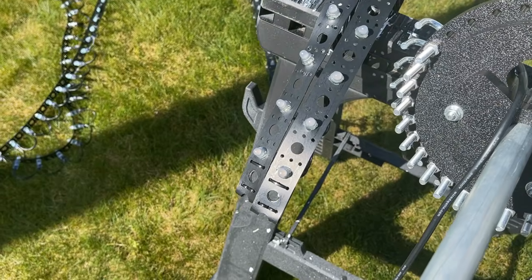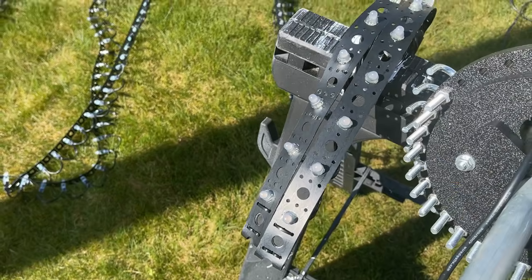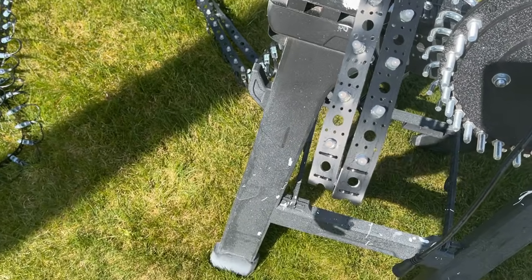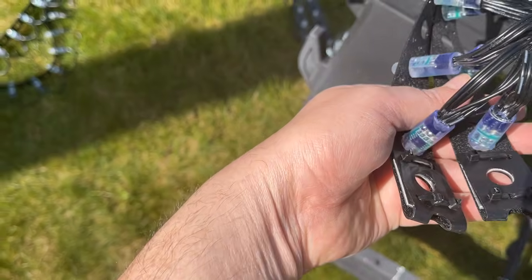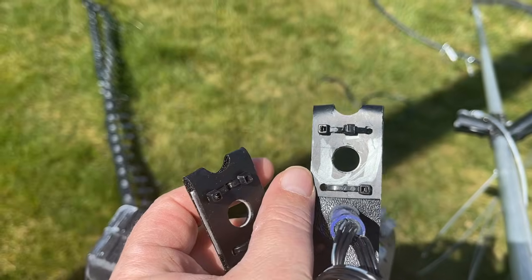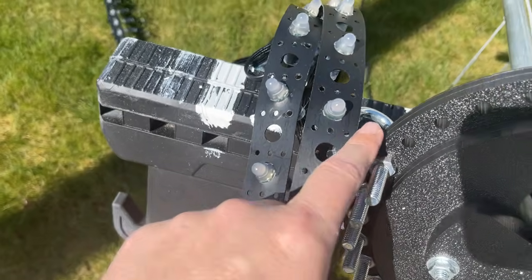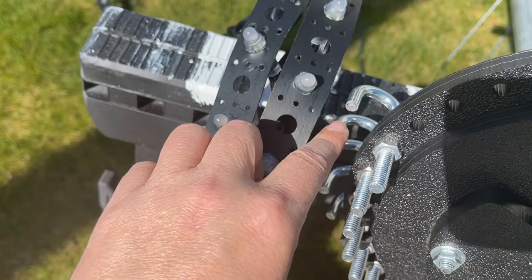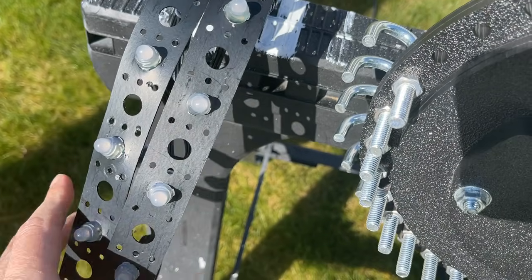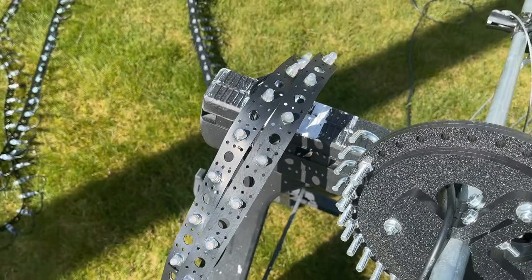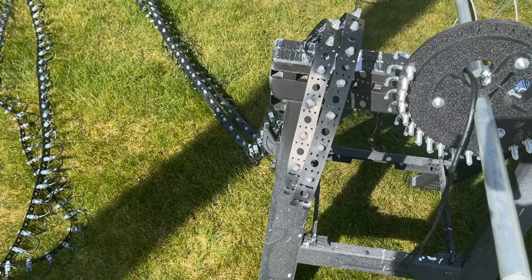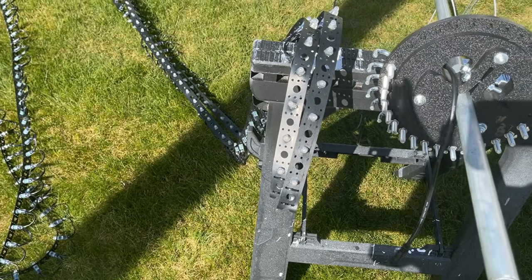So on our lights, to kind of show you here, these are 100 strings, 50 up, 50 down, and on the back, where we connect it at the top, we have the left one marked with silver paint, so we know that one goes on first, and then the other one goes on because it's got the output at the bottom. And you want to make sure you have them in the right order, depending on if you're going to run 200 per string or 100 per string. And you can go easily 200 per string, 50 up, 50 down, twice off one port.